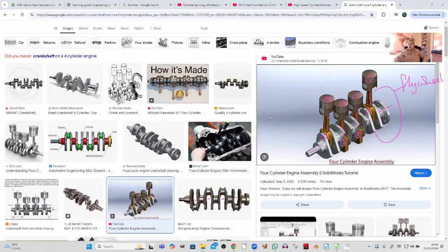Now, if you've not got 4 cylinders, if you've only got 3 or 2 or only 1, some motorbike engines are a single cylinder, then you only get a power stroke every other rotation, which means that you've got to keep the engine going round. Because if you haven't got anything to keep the engine going round, it won't keep going round the same way. So the flywheel there stores some of the energy. It smooths out power delivery. It makes the thing bearable to drive.